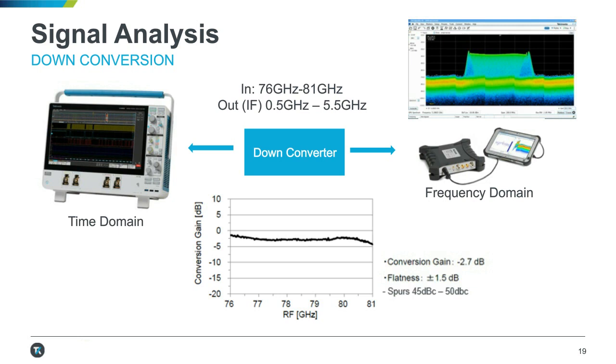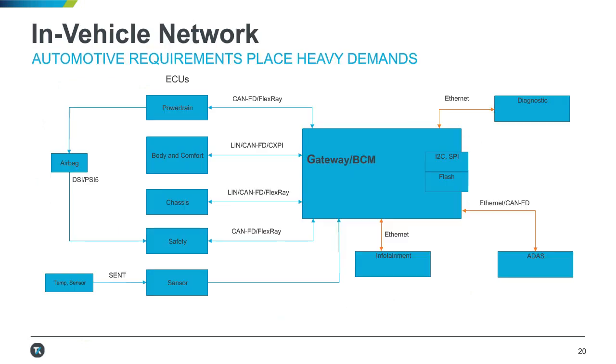Depending on how you do your sensor fusion, you're going to connect up a bunch of sensors, either as independent self-contained sensors or sensors that don't really do anything, that send large amounts of data back to a central ECU. But they're all going to sit on some kind of bus within an in-vehicle network.